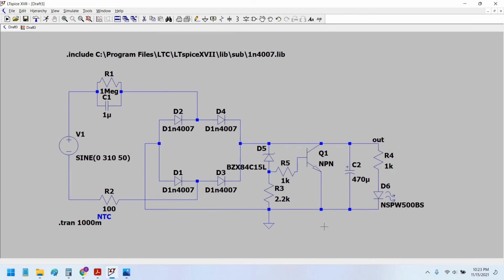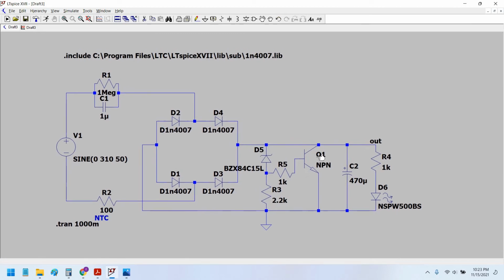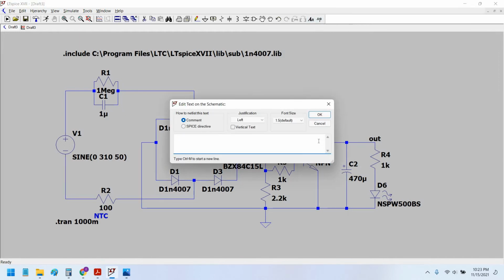Digi-Key would tell us the exact part number of the NPN BJT transistor whose VCEO is 400 volt maximum, and the maximum collector current we would use is 1.5 ampere.